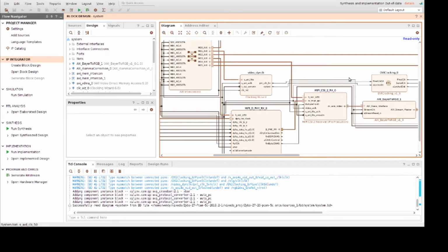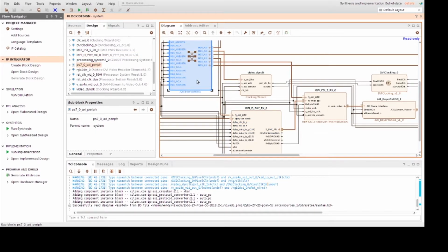And that's the whole point. By making these blocks, they already have code. Essentially, they're in essence VHDL libraries. You implement something like this, you can reuse it time and time again, and it'll save you design time.